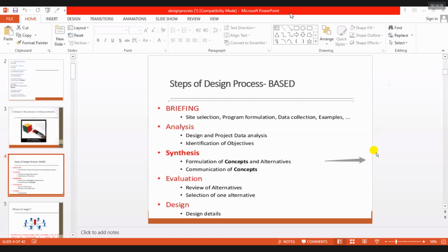Okay, we can say programming is a pre-design phase. What is the pre-design phase? Before formulation of a plan, we do site analysis. We find out a list of requirements from standards, previous case studies, books, and the client, and then we formulate our concepts and we formulate some relationships within the spaces in the form of tables or matrices. So programming is part of the pre-design phase, and your design phase starts when your floor plan is actually going to be formulated.